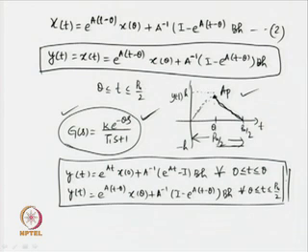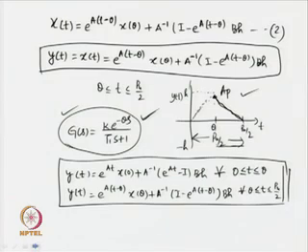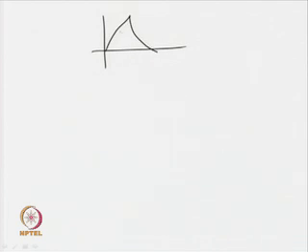Now, we shall analyze these two equations further and try to find simpler expressions that can be exploited to estimate parameters of a transfer function model. We know that the form of the output signal is like this, where we have the inputs plus h and minus h, and we are starting from time t = 0 till time t = Pu/2.